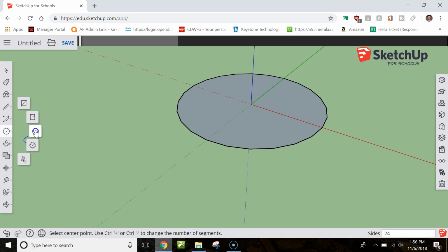Okay. Now that we have this portion set up here, the easy thing to do is going to first be to create a small, tiny little circle here, because we need to create a way for the explosive that's at the very bottom of the rocket engine to shoot through to be able to pop out our parachute. So I've just made a small little hole there, and I'm going to just delete that. So I have that small hole available.